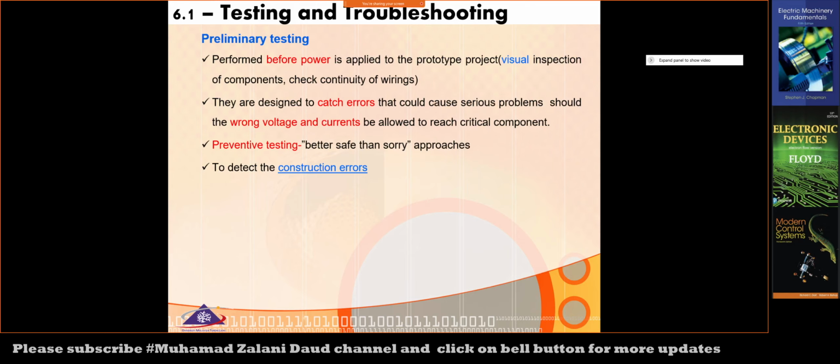For example, if I want to check the continuity of some parts of this PCB board, you can hear it. So that means the connection of those two parts has no problem. Okay, that sort of thing you can do by referring to the circuit diagram or schematic diagram, and you can do the continuity check before you give some voltage to the component, to the PCB board that you have put together.